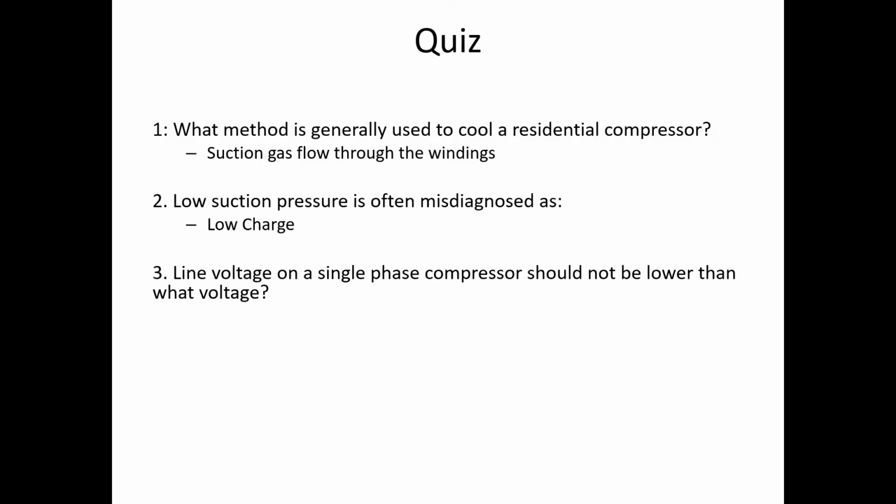So on a single phase compressor, what do you want to make sure your line voltage is not lower than? What's the lowest voltage that we can safely run our compressor? 197. Way to keep trying.